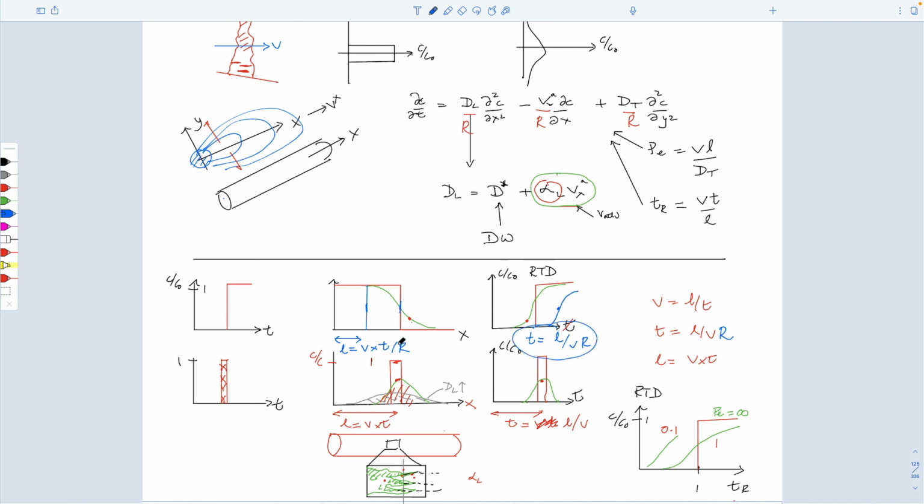So we can just take our very simple advection dispersion plug flow equations and add an extra term, and everything washes out. Everything washes out, except we still have to worry about the case that not always our 50% arrival time is at one pore volume. And so we have to reconcile that. But it will be correctly predicted if we use these conversions.